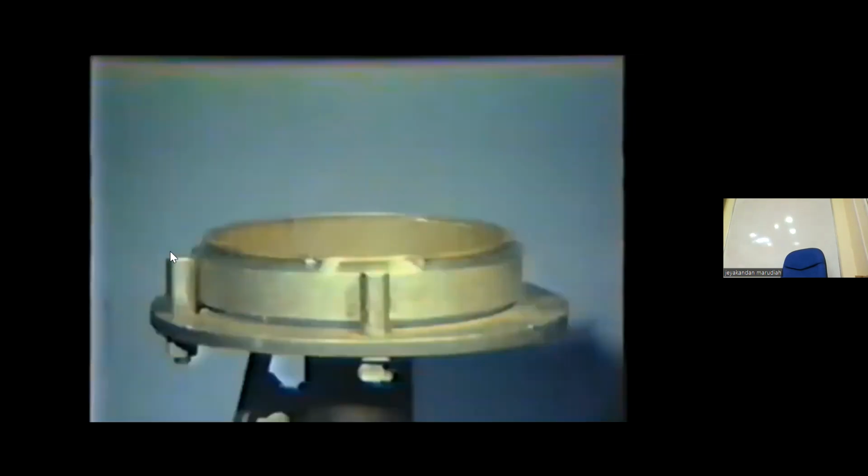Care must be taken to fit the insert accurately against the joint edge to prevent cutting off too much of the insert. After cutting, the gap between the 2 ends of the insert should not exceed 1/32 inch. Now finish tack welding the remainder of the insert using the same procedure. Place the last tack weld in the gap between the ends of the insert.